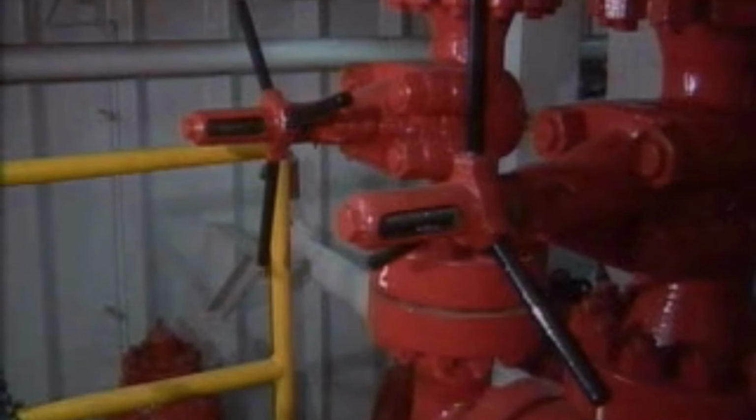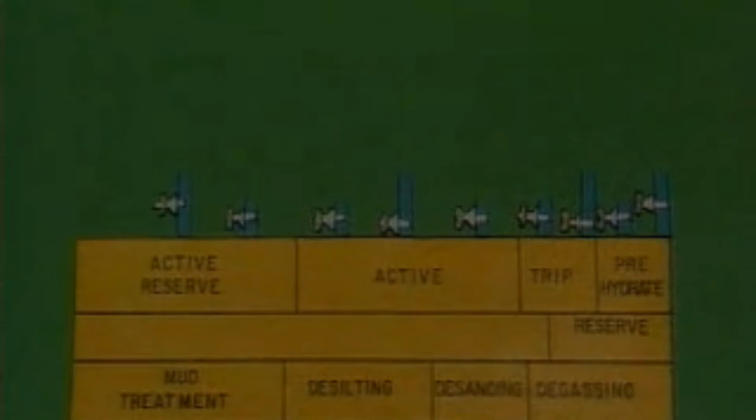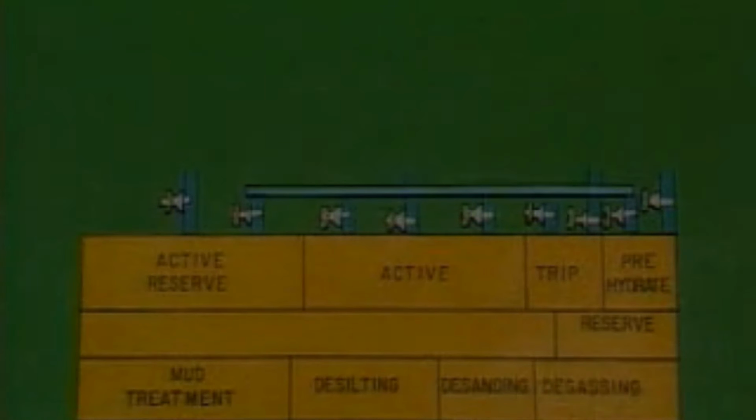We'll start at the tanks. At the bottom of each tank, you'll find at least 2 large diameter pipes and gate valves. Some will have 3. One of these 2 pipes will be connected to another large diameter pipe that runs the length of the tanks, and all of the other tanks will be tied into it. This pipe is called a suction manifold.